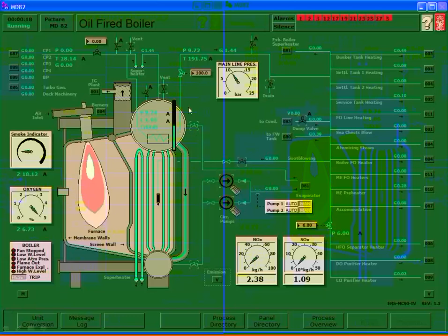So when you think about it, this boiler has 2 sets of generating tubes. One, when you're firing it on an oil fire, this set of generating tubes here. When the boiler is shut down and you're out at sea and the main engine is on, then it is being supplied from the generating tubes in the exhaust gas boiler. By definition, this is a combined cycle plant. We are raising the efficiency of the entire plant by recovering waste heat. And again, this is where steam's going.